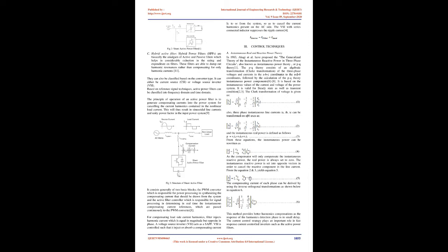B, shunt active filter. This class of filter configurations is the most important and most widely used type in active filtering. The shunt active filter is the filter that draws a compensating current from a power line to cancel harmonic currents on the source side, a grid location where power quality becomes important. It is widely used to eliminate current harmonics, compensate reactive power and balance unbalanced currents by injecting, drawing, additional current. Shunt active power filter.